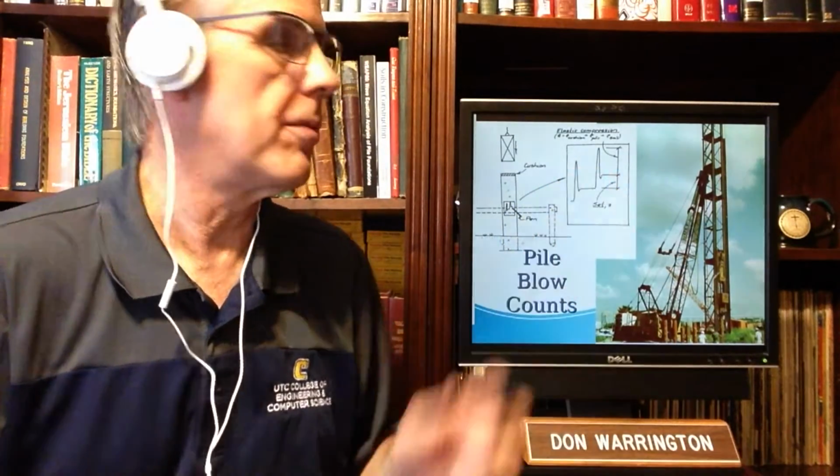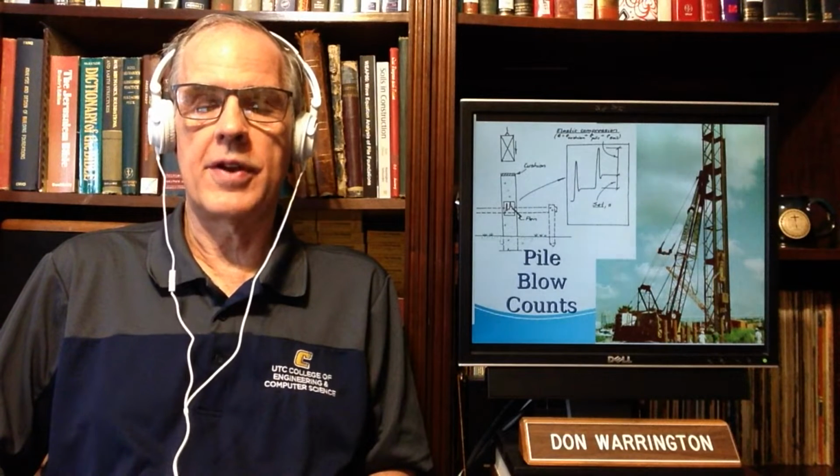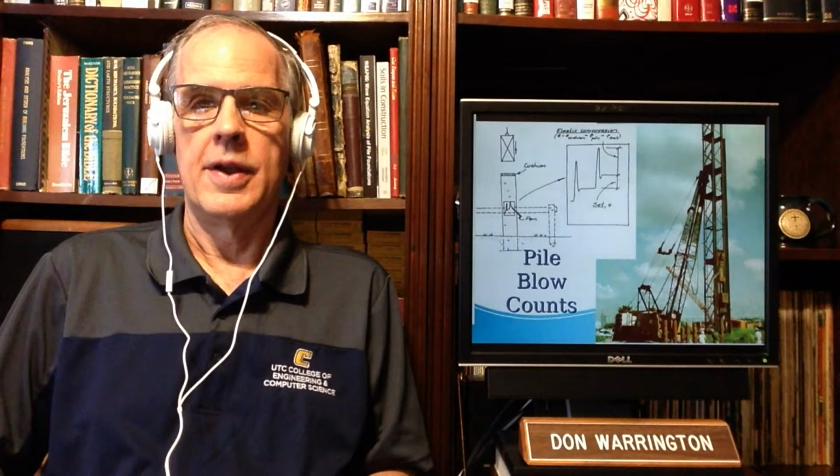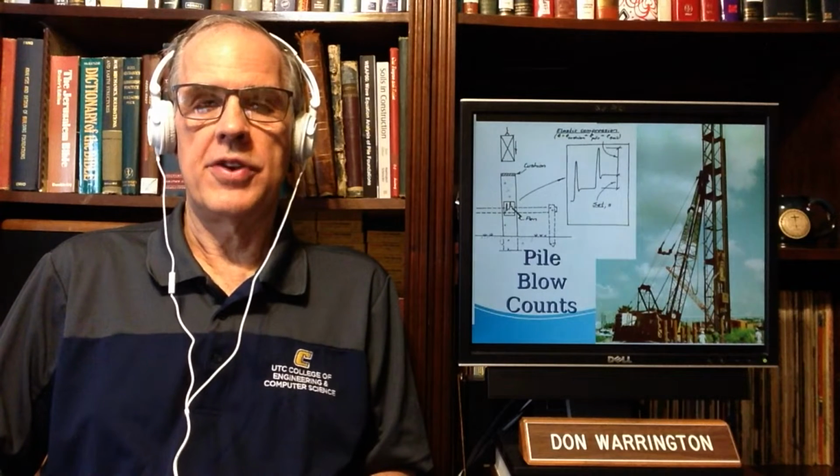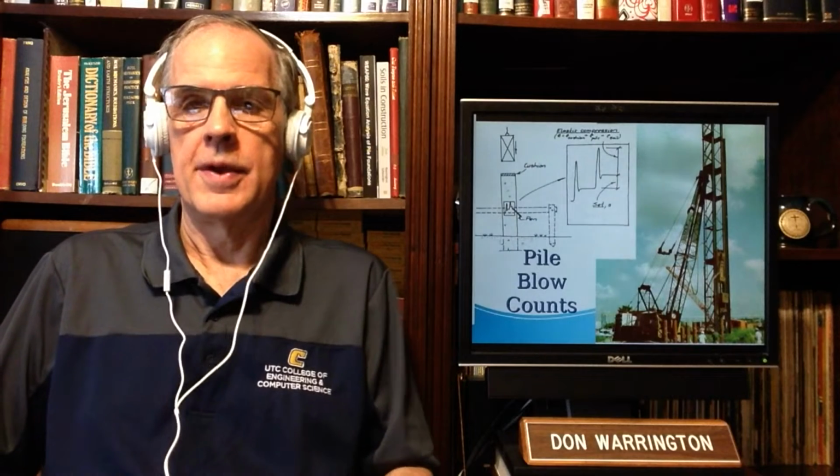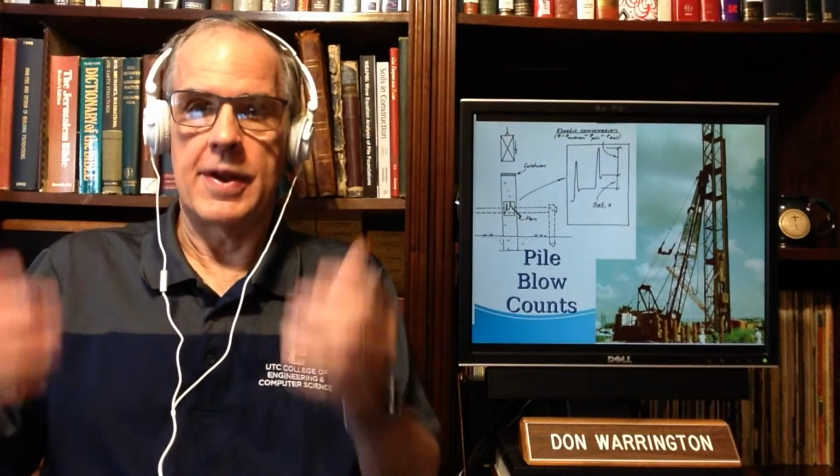Actually, this is the rebound energy. The net movement of the pile and the soil from one blow to the next is referred to as the set. That's what we experience with driven piles for the most part: as the pile goes further into the soil, the set decreases. With less set, less energy is being dissipated into the soil, and more is being kicked back up into the system. And obviously the energy we're using in driving is less effective.